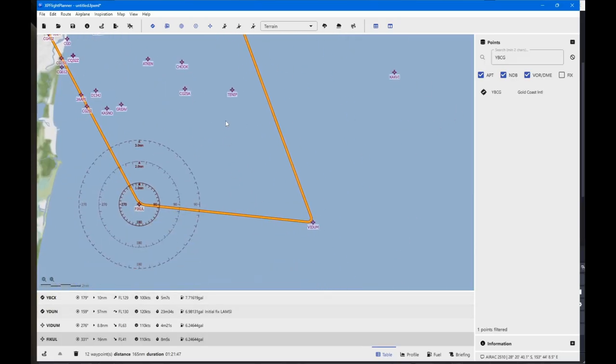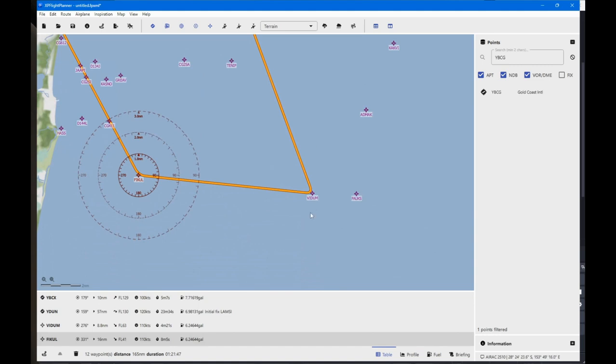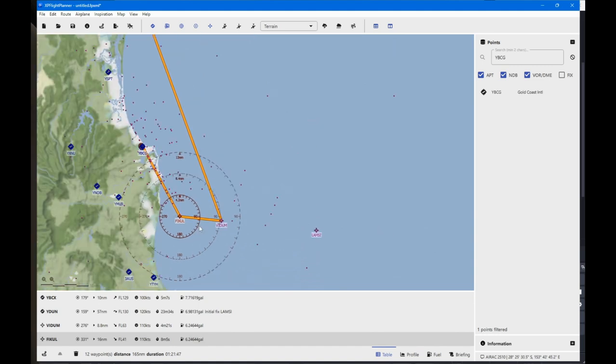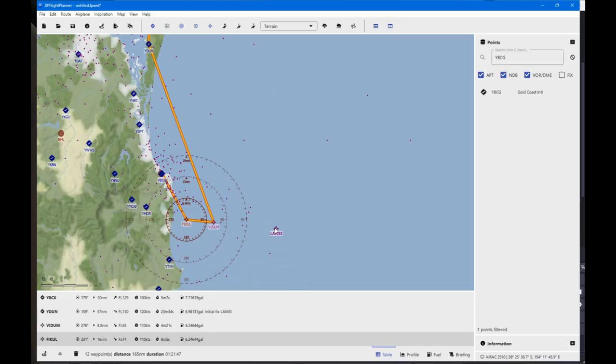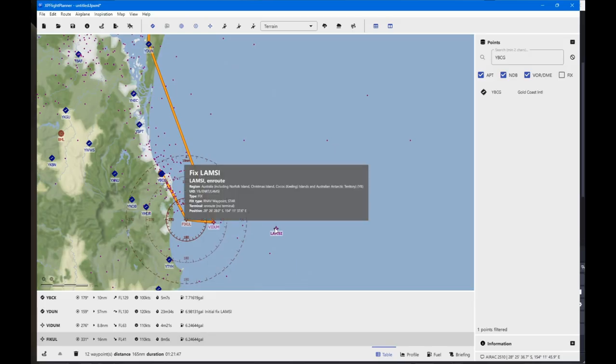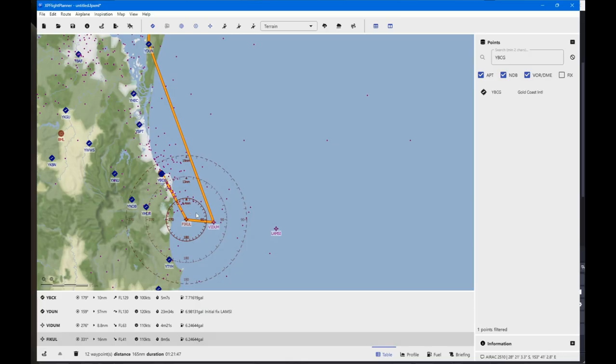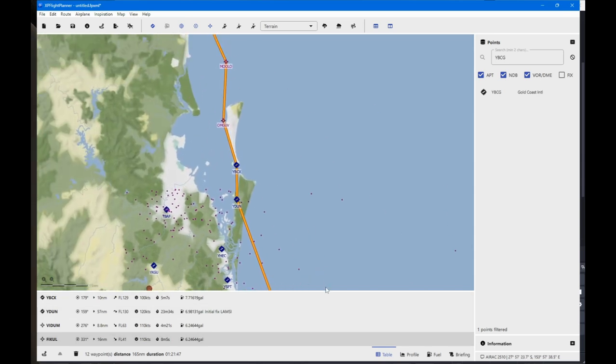so now we've got rid of the STAR, but we've got a lower level and a closer point. See, that's where the actual STAR came to, but now we've got it to here. If you didn't remove it down here, when you go and install it on your flight plan, it will come back around and loop it. It will do a funny thing. So you have to make sure that you remove the STAR from the bottom of this panel here if you want it further in.